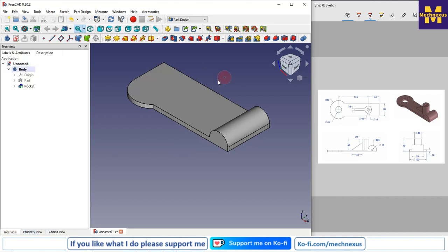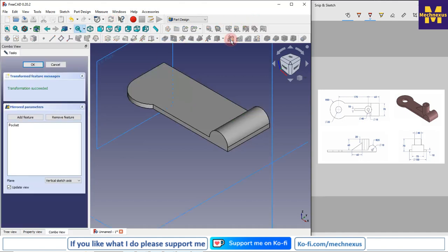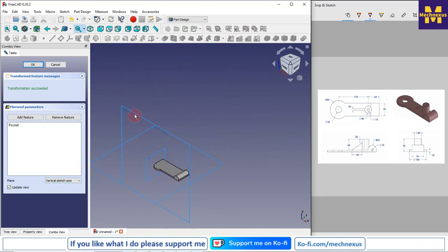And now I will mirror this to the other side. Here I am getting the blue tick, so I will update my model. Now I will select my pocket and click on mirror, and here is the plane XZ, so I will select my plane XZ. You can see that the cut has been applied on the other side as well.